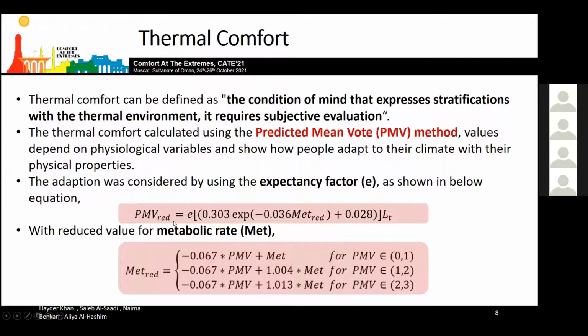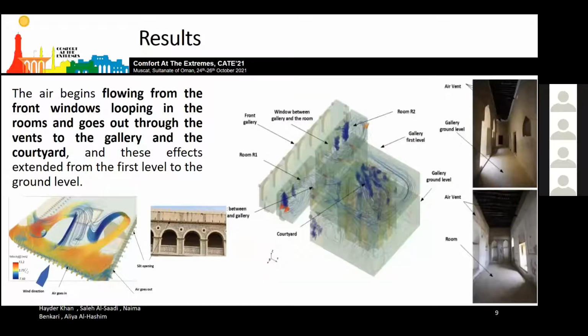We were curious about what they are actually doing, and we found it is about cooling the horizontal slab or roof level, because this receives a lot of solar energy and its temperature will increase due to that. So to cool it, they introduce a large amount of air from these openings, which comes in touch with the roof, and this will cool it, especially at night. The effect will be much stronger.